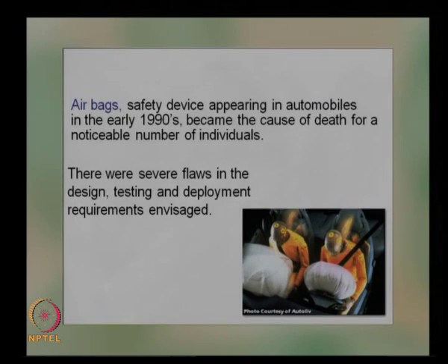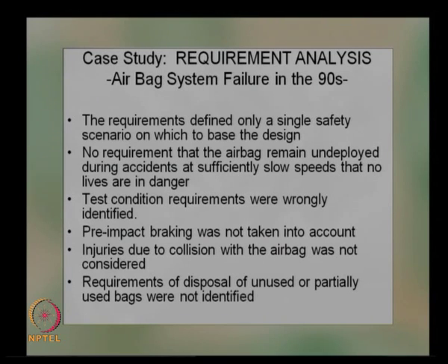So what were the basic requirements which actually failed in this case? They are listed here. As you can see, the requirements defined only a single safety scenario on which to base the design. As we discussed earlier, there were multiple scenarios of operation and use of the product, but in this case of design only a single scenario was used. Basically it was designed for a male driver driving at a speed of 30 miles per hour and having a head-on crash, and only that scenario was considered while developing the system requirement. So that was one of the faults in identification of the design requirement.